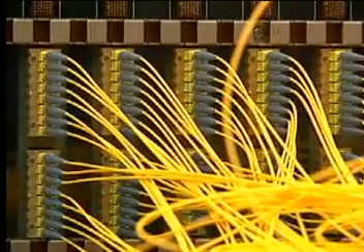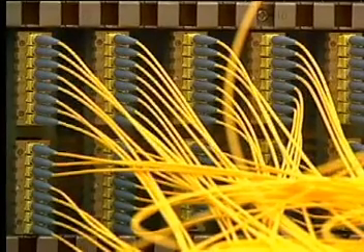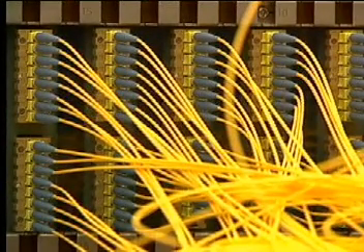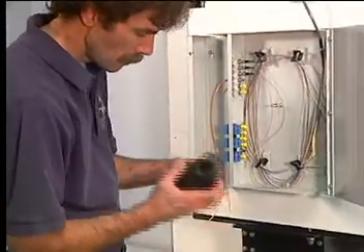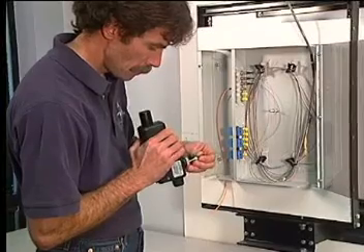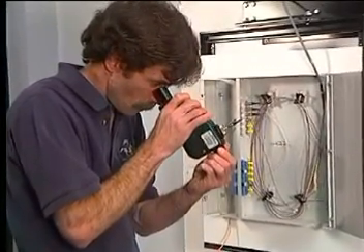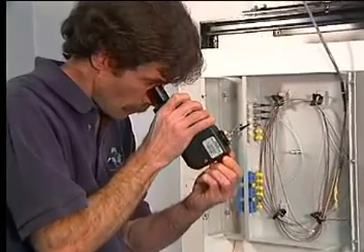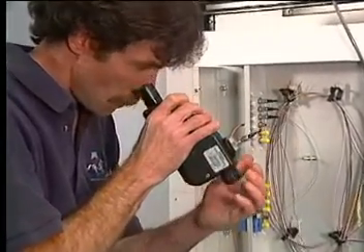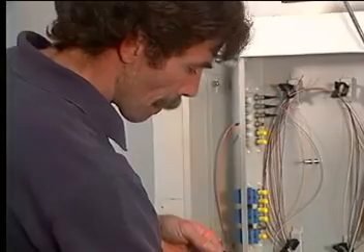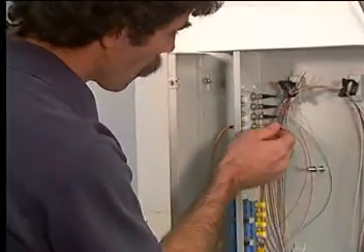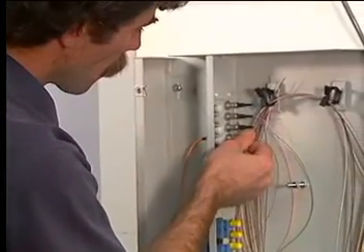Because of the many different backplane styles in use today, you must consult manufacturer's instructions for the individual style of backplane you are using. And finally, always keep your work area as clean as possible to minimize the risk of contamination. As with many other aspects of working with fiber optics, safety must be foremost in your mind at all times. Never clean or scope connectors on a live system.